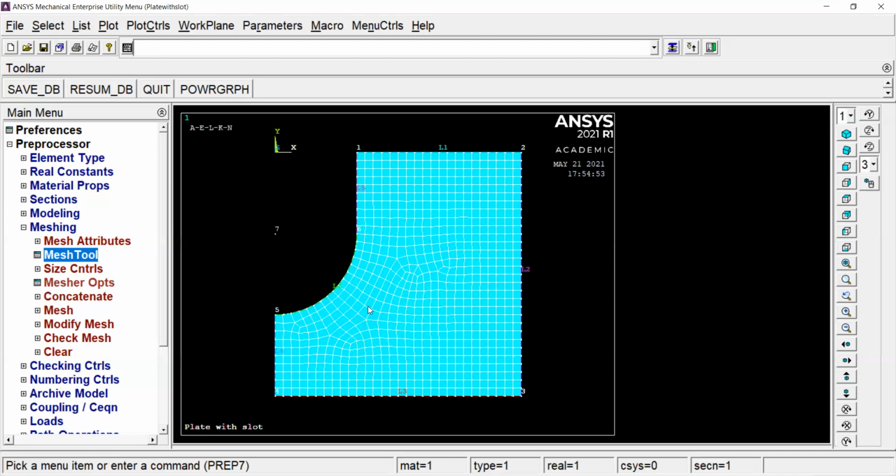So, like I said, we were trying to simulate this like it's a folded piece of paper. We're just trying to simulate a quarter of it. So the first thing we're going to apply is a symmetrical boundary condition. Remember, we halved it along the X and the Y. So we will be applying boundary conditions along the X, so line 1, as well as the Y, line 4.